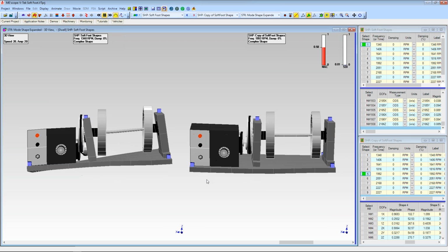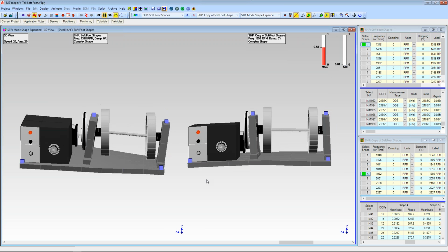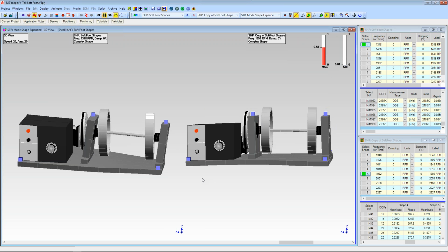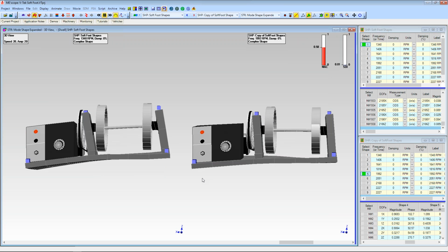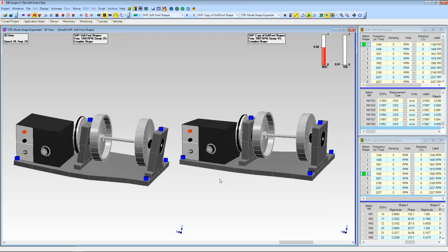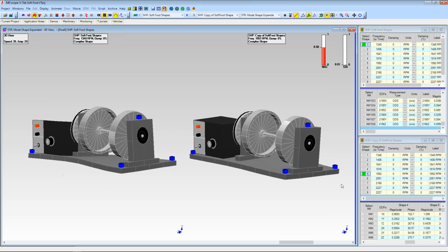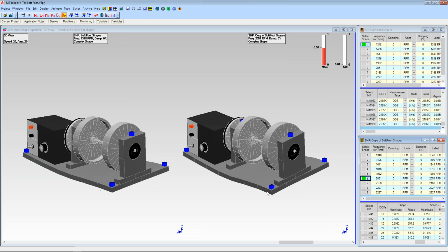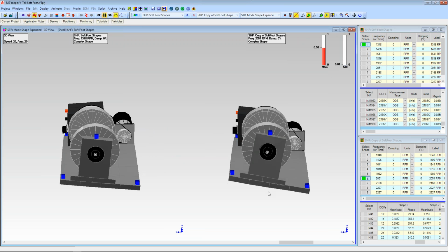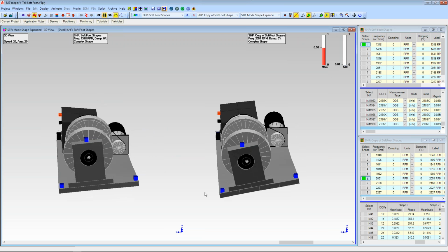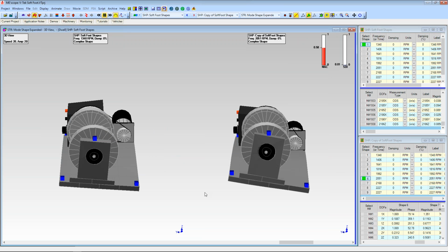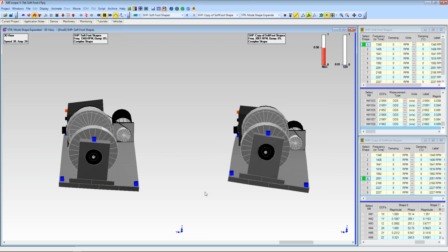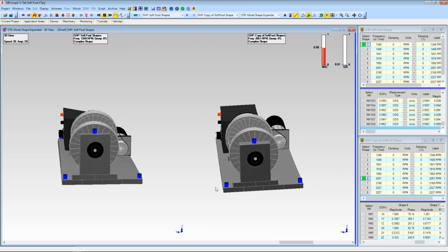And you can see a little bit of flex in the structure. Even at 1300, there's a little bit of flex there, but a lot of rigid body motion. All right, down here at 2000, we also put a little unbalanced weight on the outboard rotor to make this thing vibrate. You can see that it's vibrating quite a bit. The other thing to notice here is that these are complex. An ODS is a complex shape.